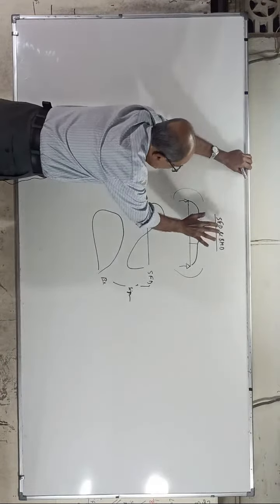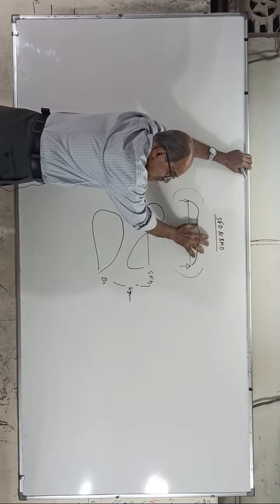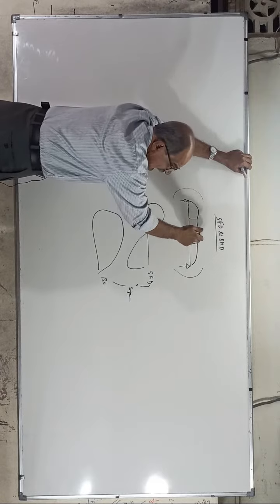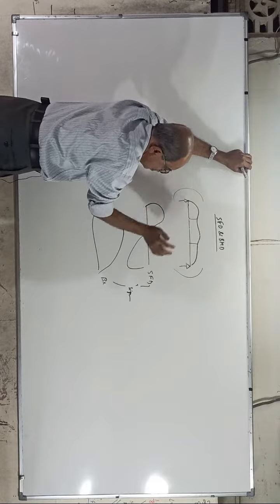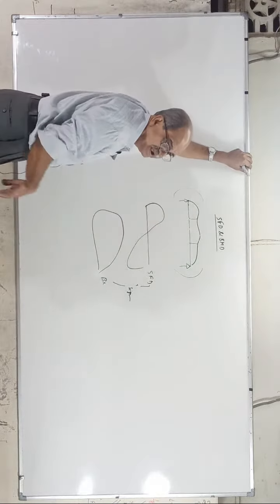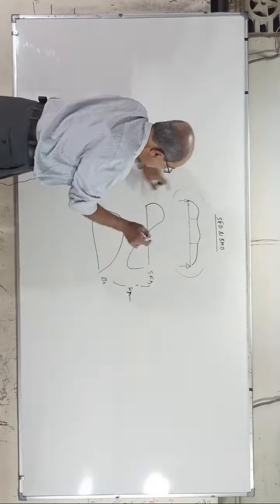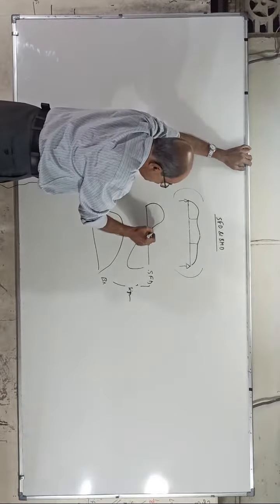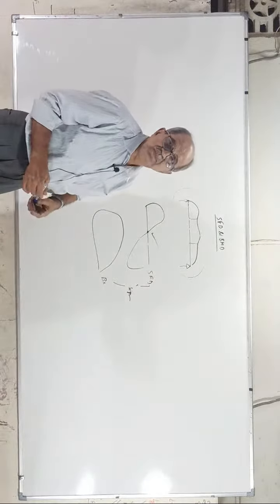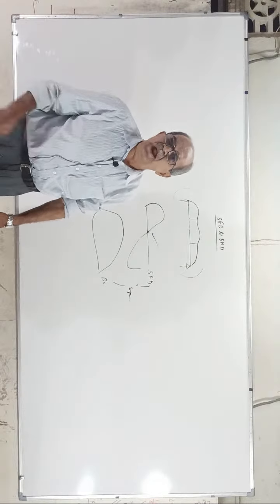So first, the loading diagram with the beam in equilibrium with the load, action and reaction. This is the action, this is the reaction. Then draw SFD and BMD. Then where SFD crosses the baseline, locate that point. If it is already a known point, keep quiet.